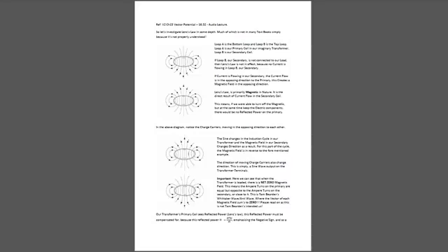If current is flowing in our secondary, the current flow is in the opposing direction to the primary. This creates a magnetic field in the opposing direction. Lenz's law is primarily magnetic in nature. It is the direct result of current flow in the secondary coil. This means, if we were able to turn off the magnetic, but at the same time keep the electric components, there would be no reflected power on the primary.